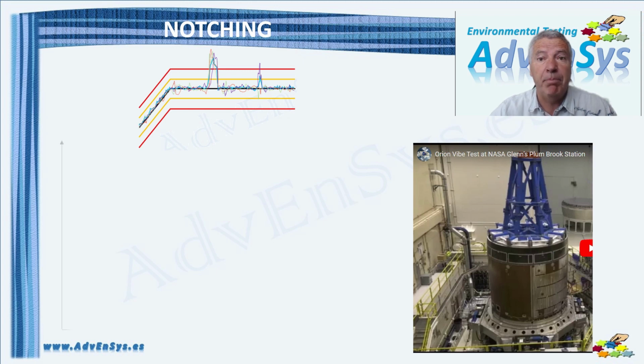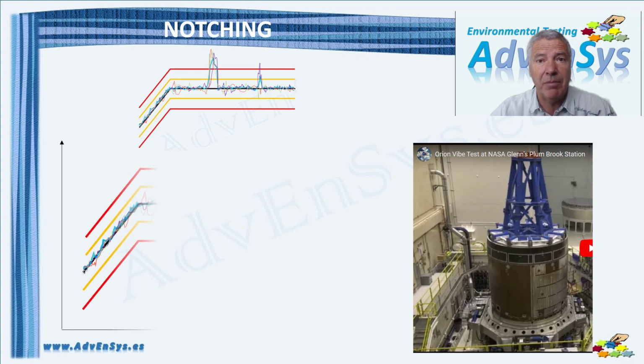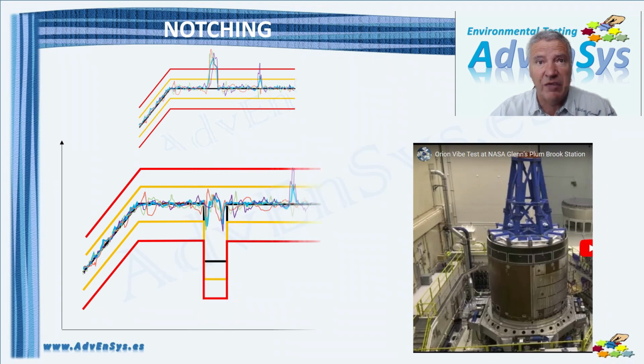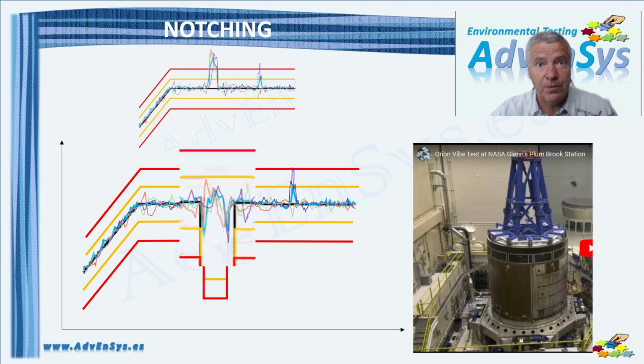It consists of a permitted reduction in the excitation level to counterbalance the extra vibration that the fixture is generating. Traditionally, the user reduces by program the reference profile within a narrow frequency band around the fixture resonance, generating a slot or notch in the reference profile. The control adapts to reduce the drive signal, and the free acceleration also reduces, getting closer to the reference. Now let's see a detail of the notch.